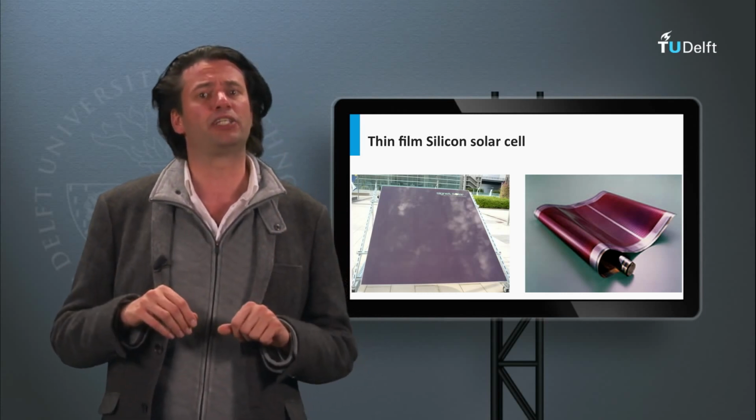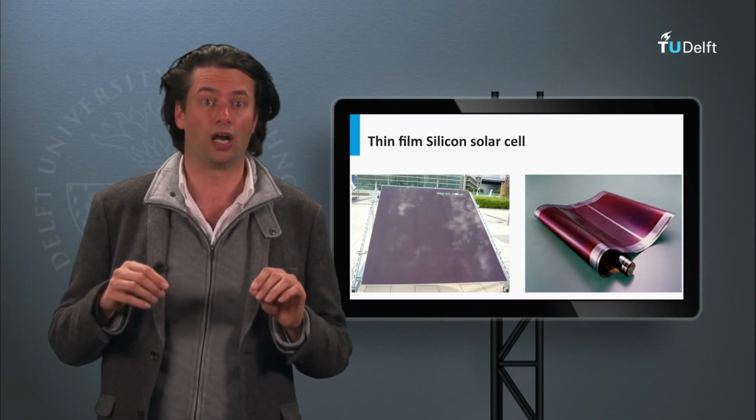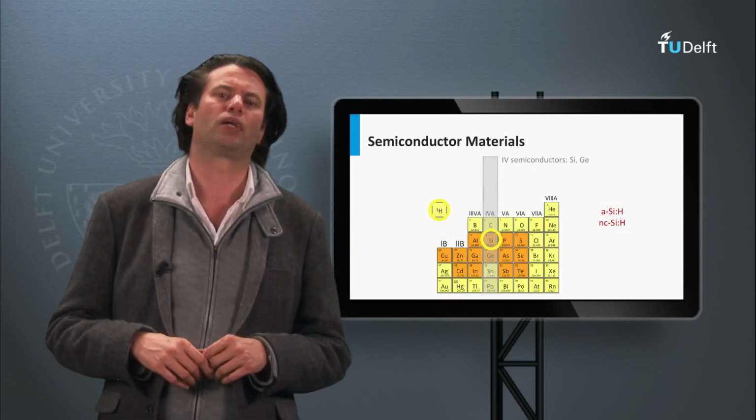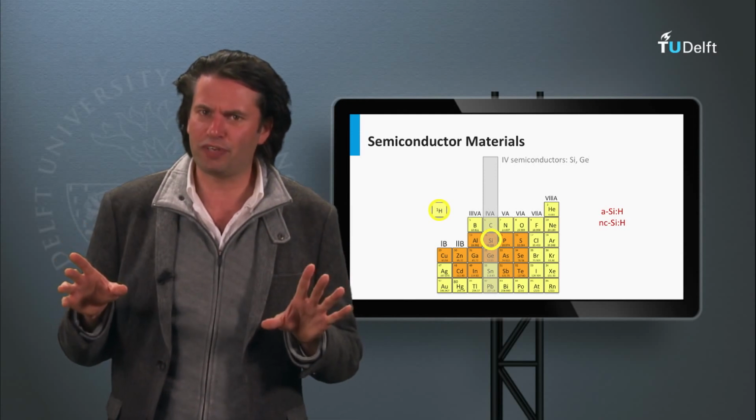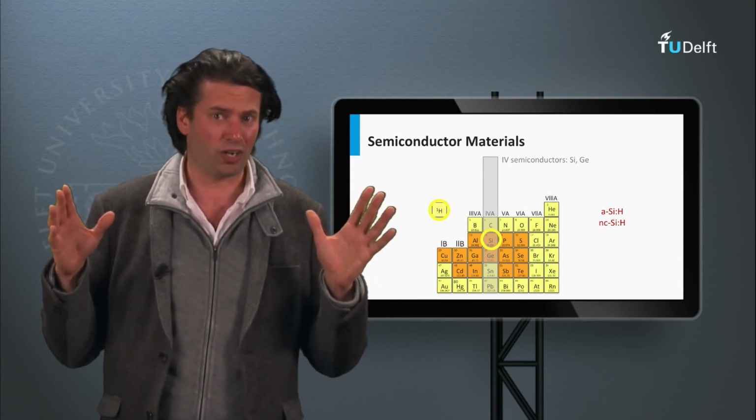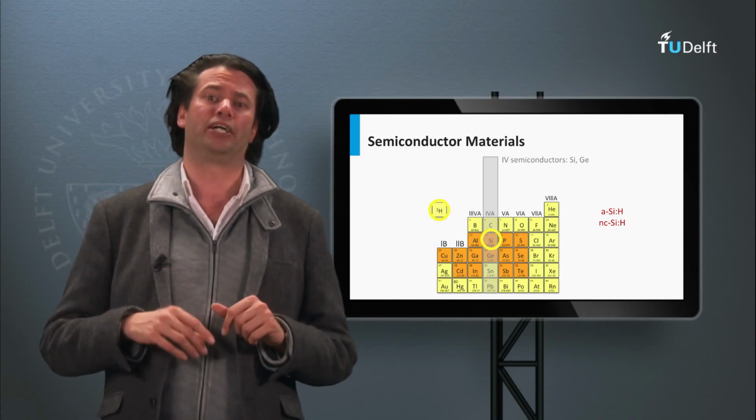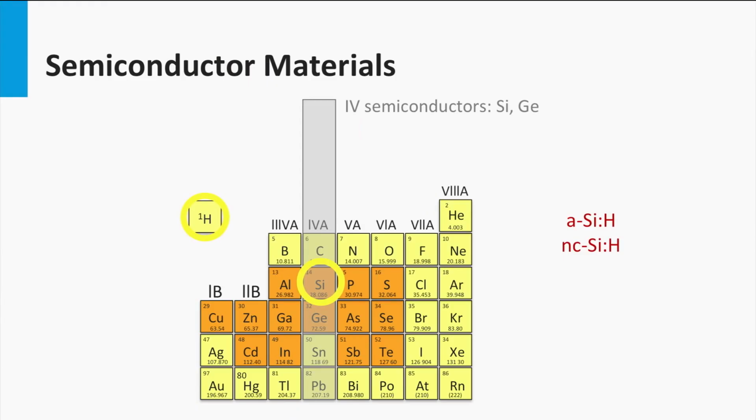An advantage of thin film silicon solar cells is that they can be deposited on glass substrates and flexible substrates. So the first question we have to answer is, which type of silicon alloys are being used as an absorber layer? The typical lattice structure is either amorphous or nanocrystalline. Nanocrystalline is also called microcrystalline in the literature. In a moment I will come back to how these lattices really look. A-dash is the abbreviation of amorphous and C-dash is the abbreviation for nanocrystalline silicon.